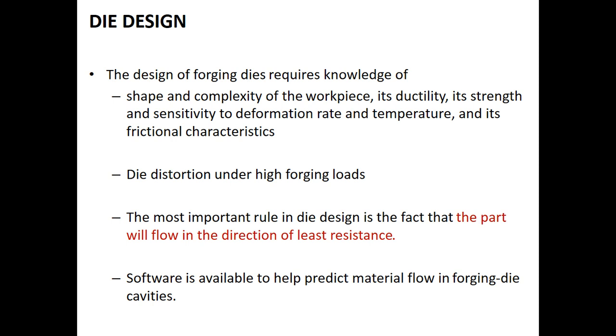The design of forging dies requires the knowledge of shape and complexity of the workpiece, its ductility, how much ductile it is, I mean it's a material characteristic, its strength and sensitivity to deformation rate and temperature, and its frictional characteristics.